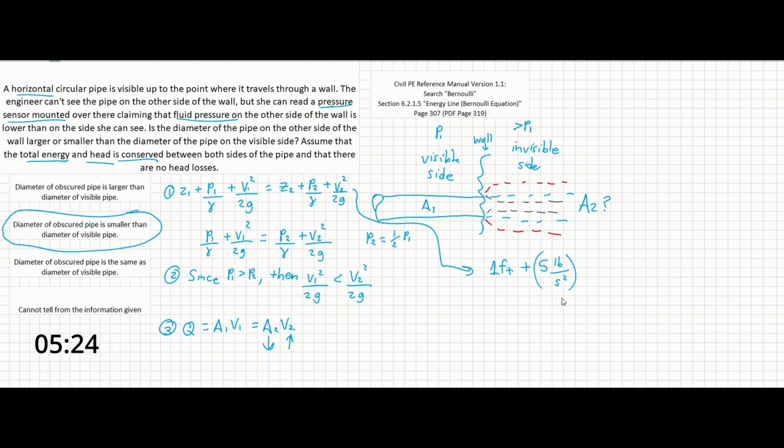Saying it out loud helped me catch that. So the gamma in this case is the specific weight of water, which is going to be 62.4 pounds per cubic foot. And oh, I made another mistake up top. I was thinking about velocity for some reason. So it's pounds per foot squared over pounds per foot cubed, which is how it's going to end up with a foot unit at the end to match up with this one.